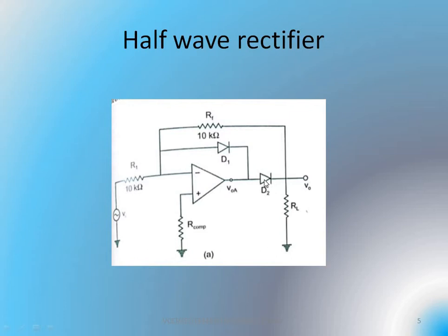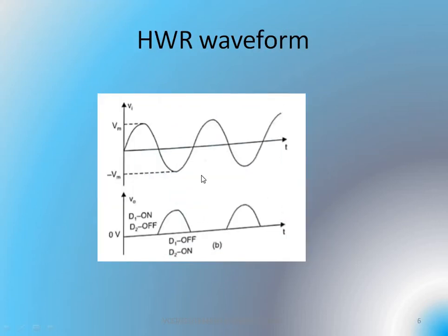And this D2 acts as a closed circuit, and this closed circuit is closed via the feedback resistor Rf. So here you can find that the circuit behaves as an inverting operational amplifier. This inverting operational amplifier will amplify the negative half cycle that is applied. So here the picture will give a clear image.